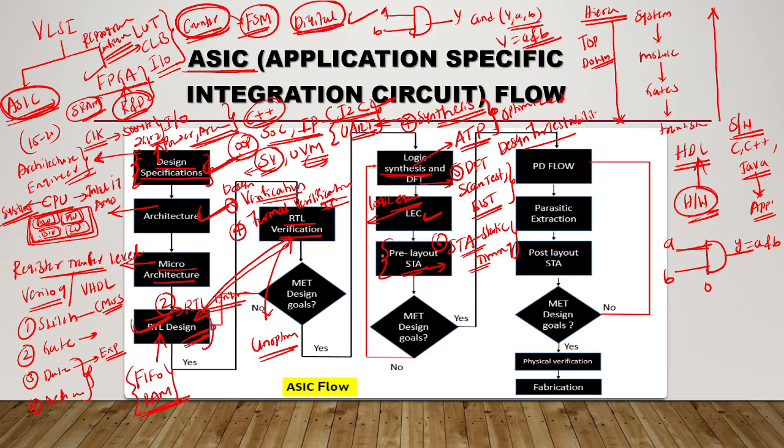This is one type of simulation only. Here we do the simulation by using waveforms. But with the help of this, working on delay-related, timing-related things, they will use it in static timing analysis. Okay, and if the design is not met, again it will go to the synthesis. If the design is met, it will go to the PD flow.